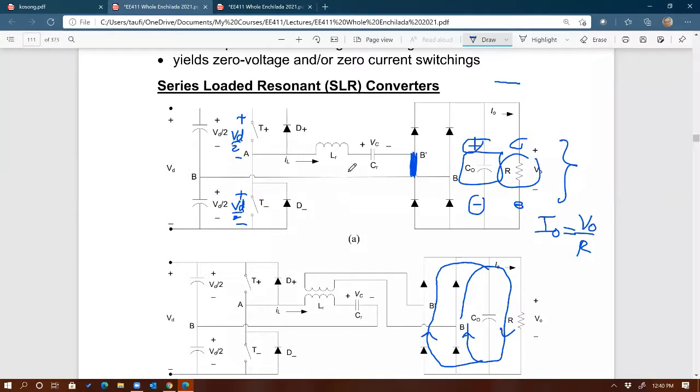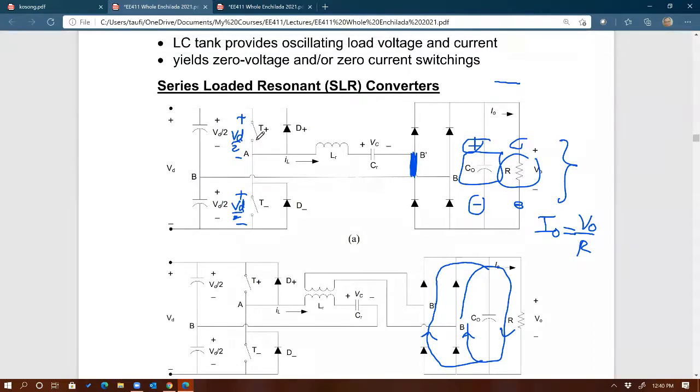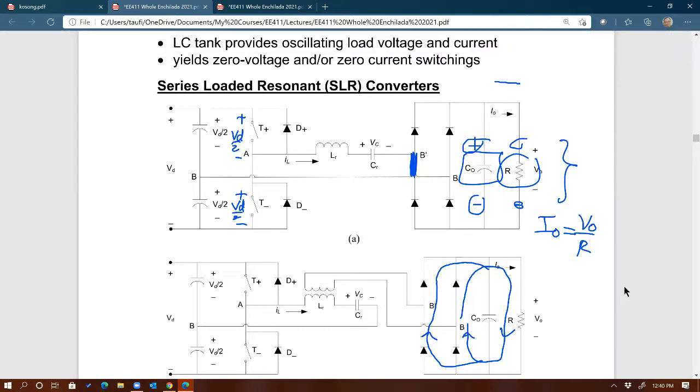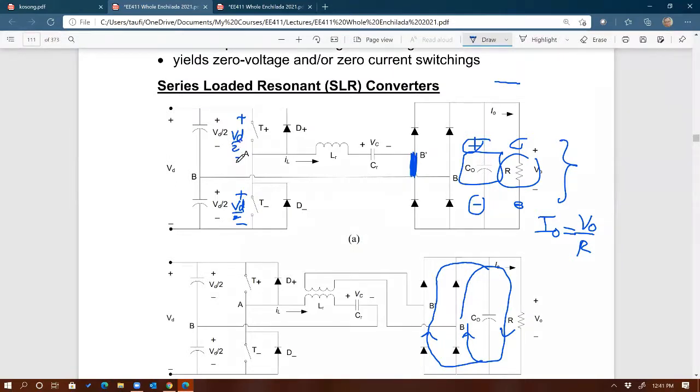Right, exactly. So by analyzing the circuit this way, using this KVL, it looks like, to me at least, it's easier to determine, number one, that it is not 0 voltage when it turns on. Number two, I know exactly what that value of the voltage is before it turns on, which is VD. You can see how it's multiples of VD. Yes. Oh wait, no, VD minus V. Never mind, ignore me. It's a factor of 1/2, right? So it is a multiple of VD. In this case, the multiplier is 0.5 because it's a half bridge, right?